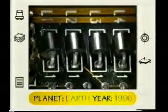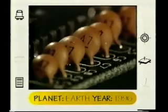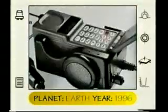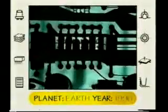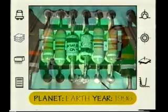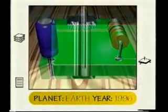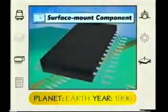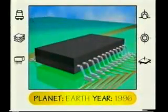Electronic components are used to change electrical current flow in different ways. They come in many different shapes and sizes, and are used for a great variety of purposes. When mounting electronic components onto printed wiring boards, or PWBs, there are two primary types of components: through-hole components, which have leads that are fed through holes in the PWB and then soldered, and surface mount components, which are soldered directly to the surface of the PWB onto thin metal areas called lands or pads.